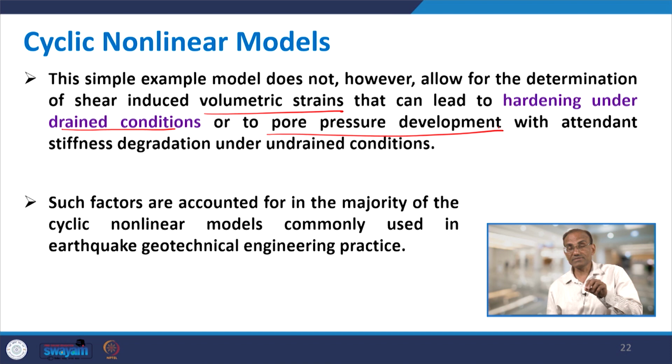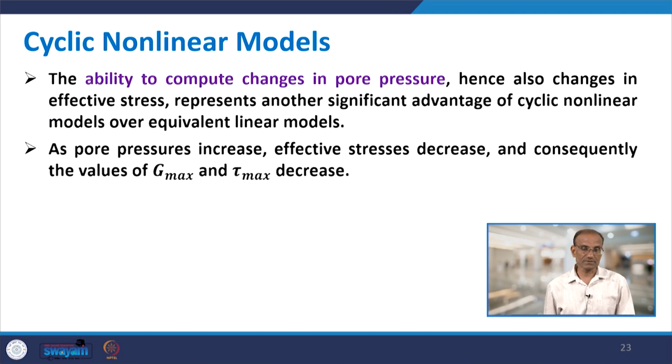So, in the model which we have considered, volumetric strain or development of pore pressure was not considered, but it is possible in the cyclic nonlinear model. Such factors are accounted for in the majority of the cyclic nonlinear models commonly used in earthquake geotechnical engineering practice. So, the ability to compute changes in pore pressure, hence also changes in effective stress, represents another significant advantage of cyclic nonlinear models over equivalent linear models.